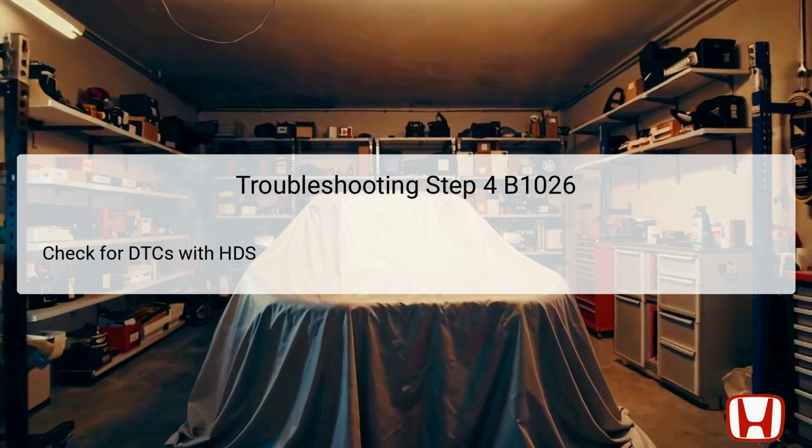In the fourth step, the focus shifts back to checking for DTCs using the HDS. After operating the door lock switch, it's vital to see if the B1026 code reappears. If the code is displayed again, this confirmation indicates that the system has a persistent issue, warranting further investigation.